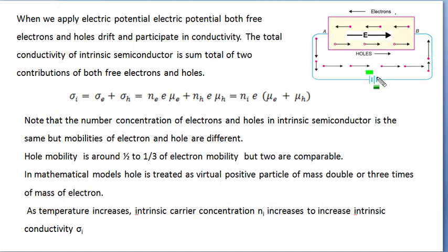material. When we apply external voltage, there exists an internal electric field which is directed from high potential to low potential in semiconductor material. Now this electric field shifts thermal motion of free electrons as well as holes in one particular direction, and electron will drift opposite to the direction of electric field, and hole will drift in the direction of electric field.